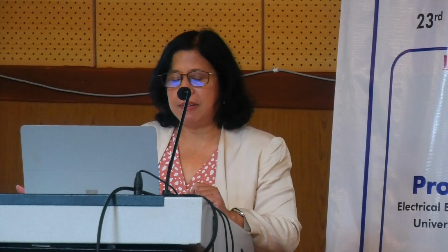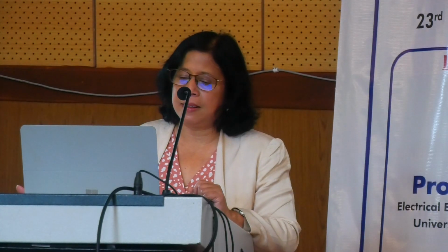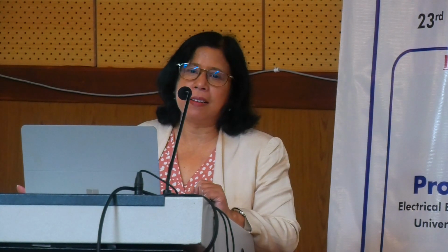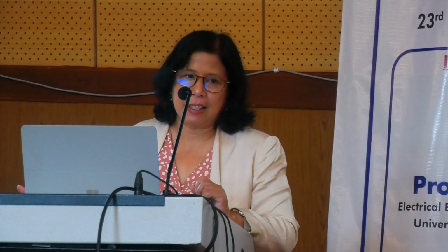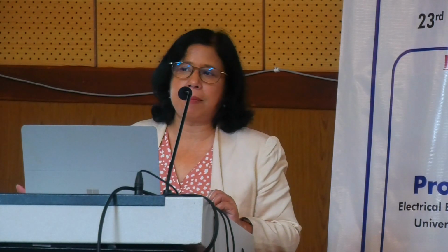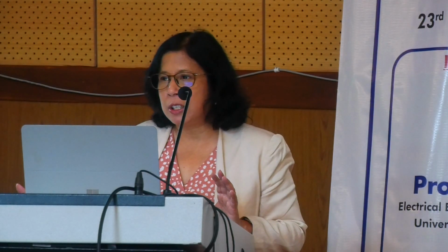That's why we always have leakage, and there could also be fringing depending on the shape of your pole and tooth, etc. So again, the estimation of leakage flux is quite difficult analytically, especially in interior type permanent magnet machines, where there is flux leakage, as you will see later.